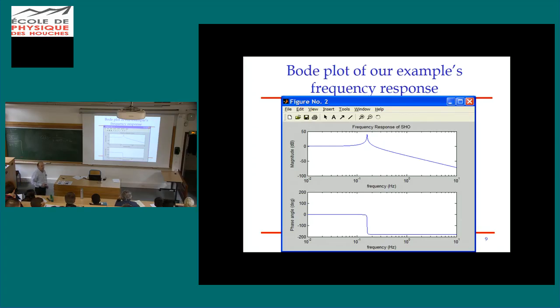Okay, yes? For a linear system, the output will have the same frequency, resonance or not. Let's examine it for this case where there is a resonance, but that's the beautiful thing. That's what makes this work, that the output after startup transients. I should say, if I want to be 100% correct, what I'm showing you is true in the limit that I started applying the input an infinite amount of time ago, so that any possible autonomous dynamics of the system that came from kicking it at the start have damped away.